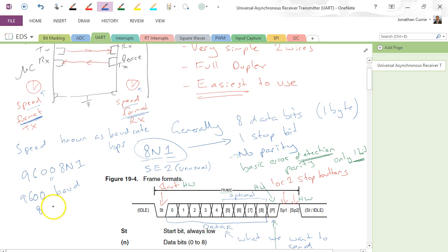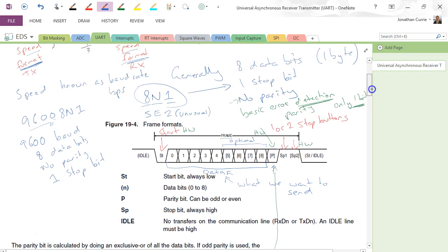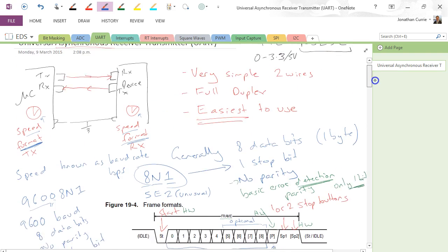8 data bits, no parity, 1 stop bit. And that's a very common format to be started with, and speed. Right? It's a really nice one. I suggest you use it. If you need to go faster, there are other common ones which we're going to look at later on, but that's one of the slowest, easiest ones to work with. Slow is good, it avoids errors. Right? The only problem, or transmission errors, the only reason you go any faster is if you've got data rate problems. You need to send more data.